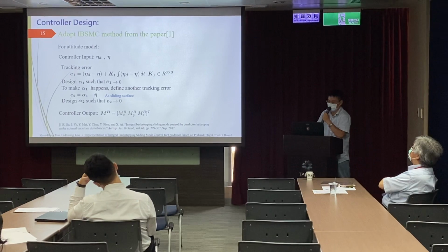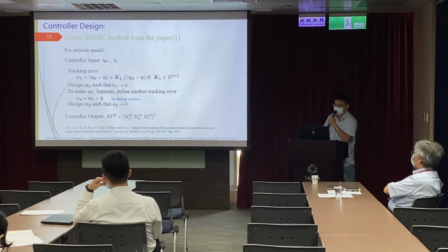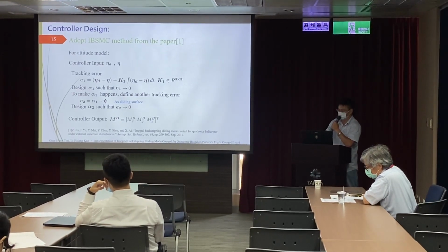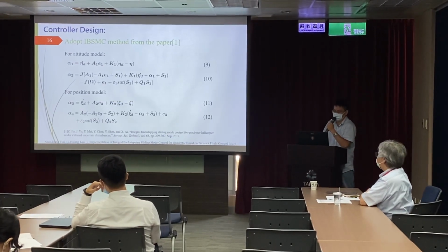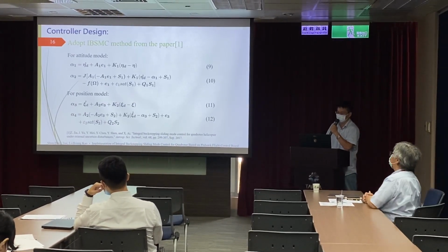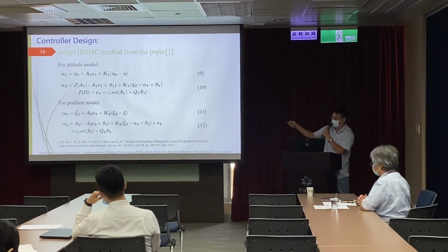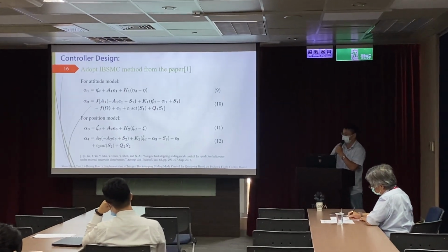And for attitude, IPSMC is the same way. The input is attitude tracking error, and the output is torque that makes roll, pitch, and yaw. And we adopted IPSMC examples from the journal as shown for equation 9 to equation 12, and all of them could be verified by the Laplace theorem.